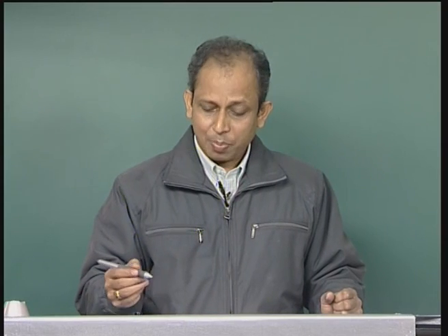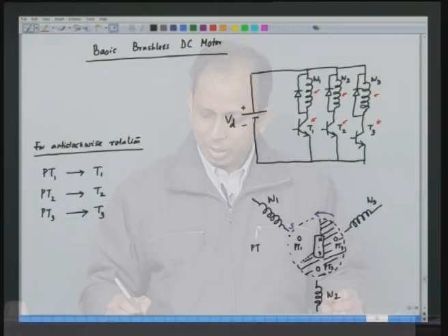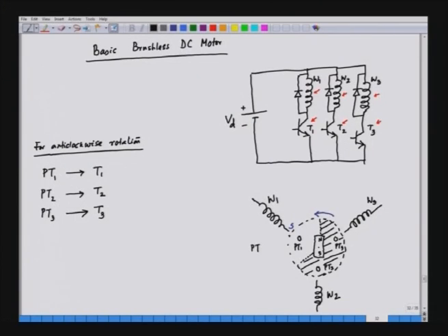The rotor rotates in the anti-clockwise direction. After some time, PT1 will be covered and PT2 will be lighted, and hence the pulse will be applied to W2, and then after some time PT3 will be lighted, and hence the rotor will continuously rotate in the anti-clockwise direction.